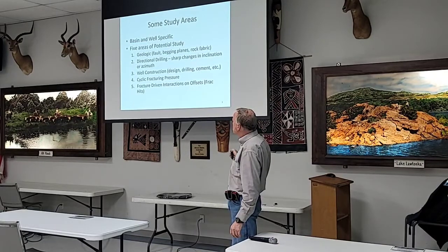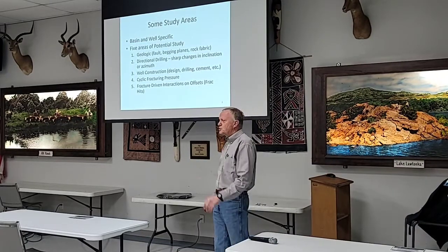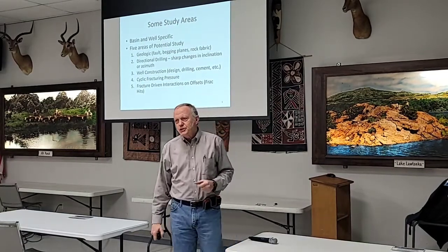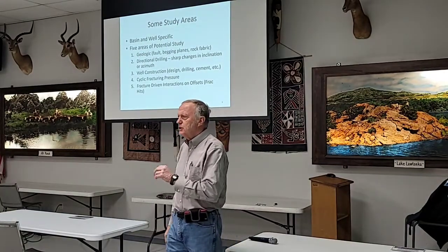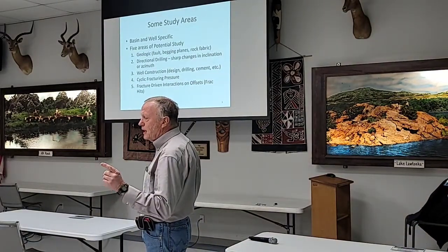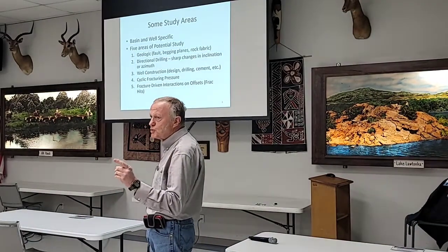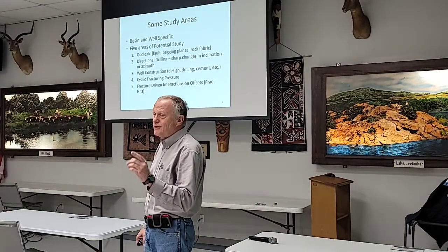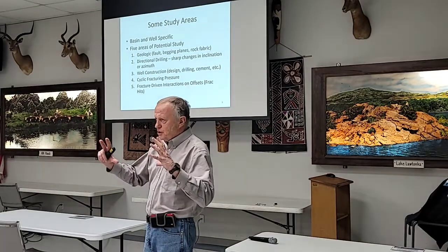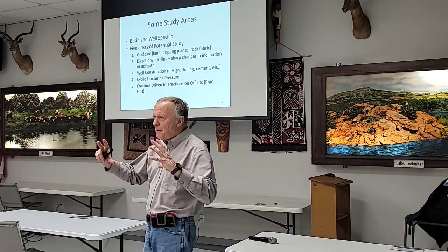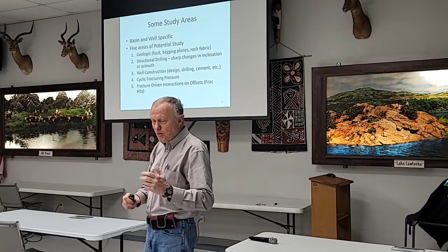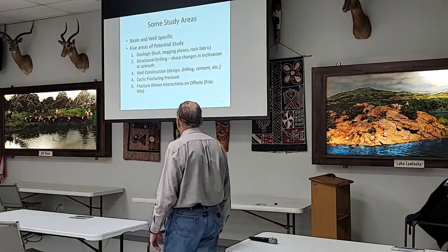There's a couple of things you can do when you're doing this well construction that will minimize the amount of casing damage that you have. And I'll just give you a little preview here. Use a heavier wall pipe if you're in an area which is prone to some kind of ovoid. This is one thing we found at Viking, is that when you start getting into a light wall pipe, you collapse that a little bit easier, or oval it, not maybe completely collapse.